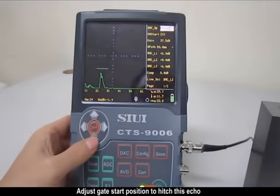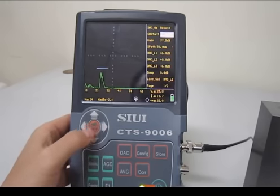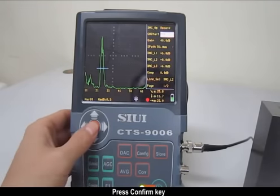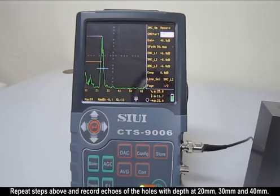Adjust gauge start position to hit this echo. Press AGC key to bring the echo amplitude around 80%. Press Confirm key and the first echo reference point is recorded and the first curve section is drawn.